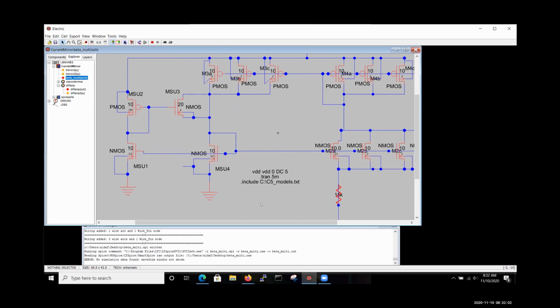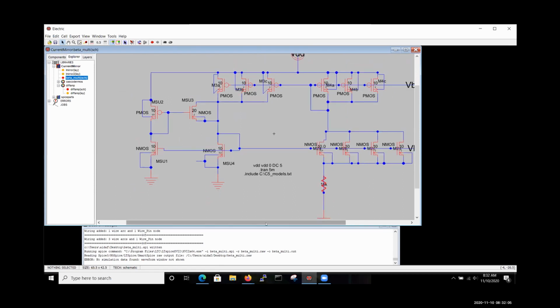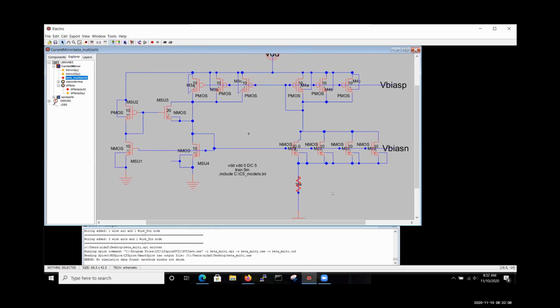All right, so you got a 10x2 NMOS down here in the bottom left, a 10x100 PMOS, a 20x2 NMOS, 30x2 PMOS, 30x2 PMOS, 40x2 PMOS, 10x2 NMOS, 15K resistor. All right, so now you got all the right sizes. So let's start checking these connections.